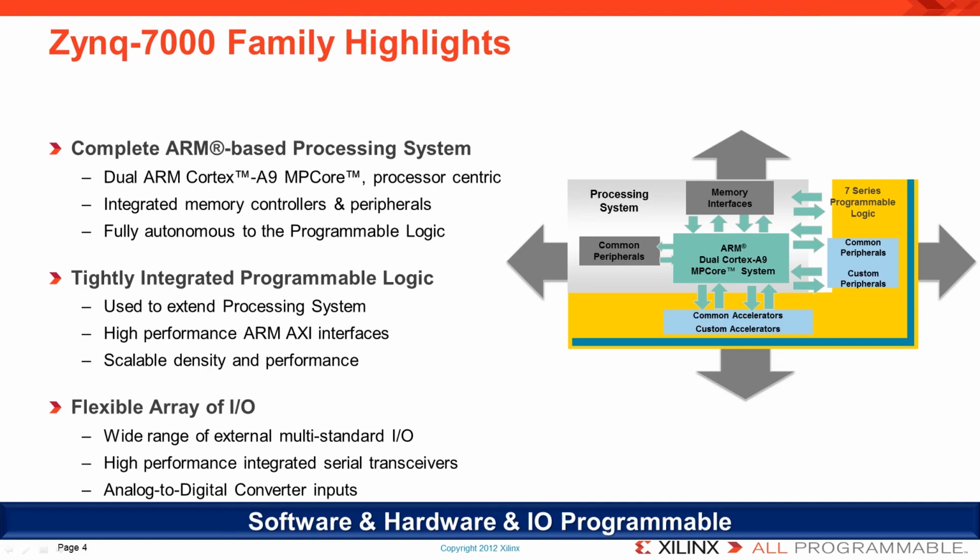The Zynq-7000 device, comprised of a dual-core ARM Cortex-A9 processing system and peripherals, and Xilinx's most advanced programmable logic, enables product developers to add peripherals, accelerators, and other functionality directly into the Zynq's programmable logic without the need to solder another discrete part to the board. These custom IP cores, instantiated within Zynq's programmable logic, connect to the processing system just as the built-in hardened blocks of the processing system itself are connected, through AXI interconnects. The result is higher performance at lower cost and complexity than previously discrete designs.